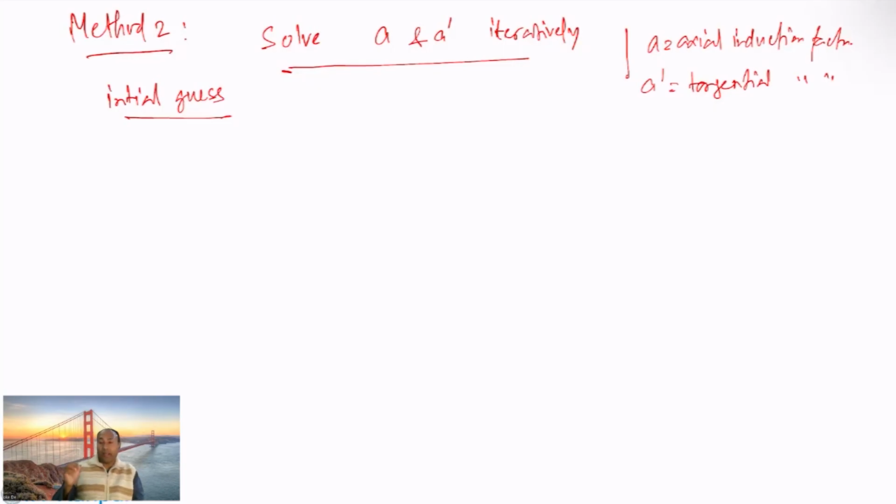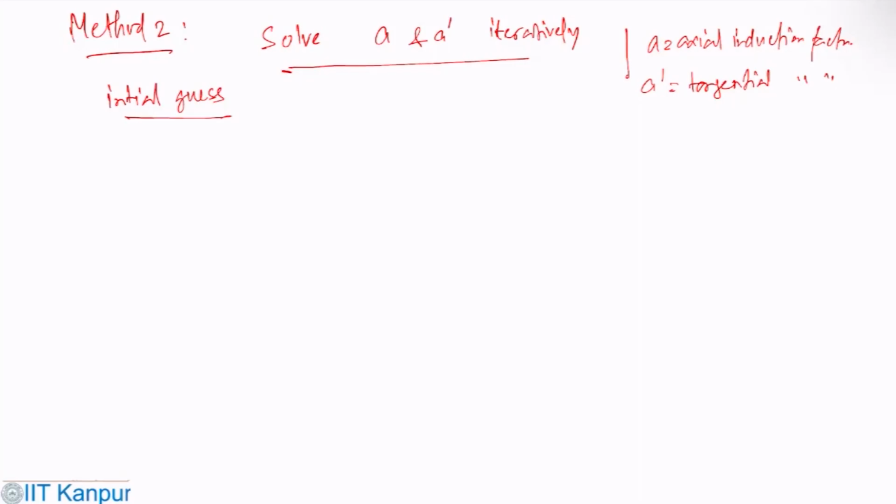To find initial values, we start with the values from an adjacent blade section, or values from a previous blade design in the iterative rotor design procedure, or use an estimate based on the design value.